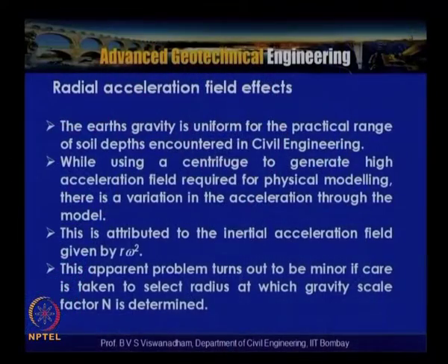So after having discussed the possibility of the geotechnical centrifuge studies, we said that by subjecting a model to rotation about a vertical axis in a rotational plane, there is a possibility of these radial acceleration field effects. What we said is that these effects affect the vertical stress, and consequently they also affect the horizontal stress distribution.